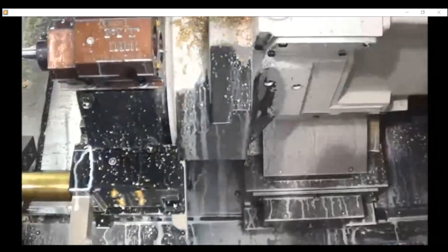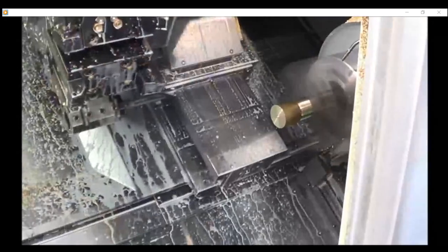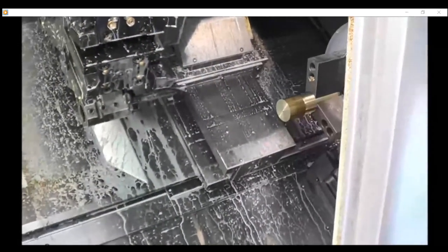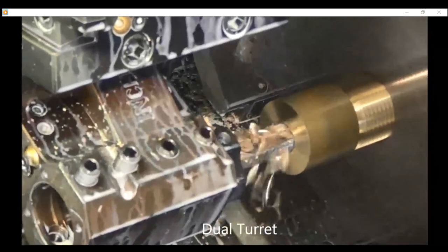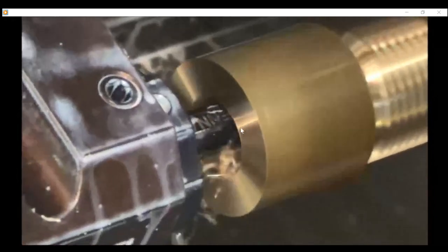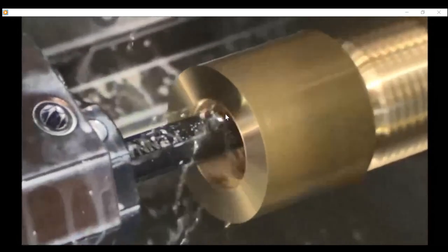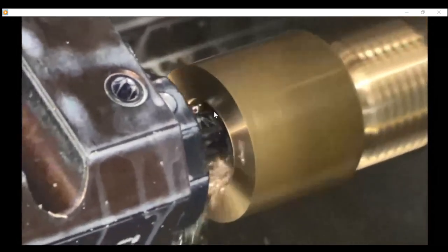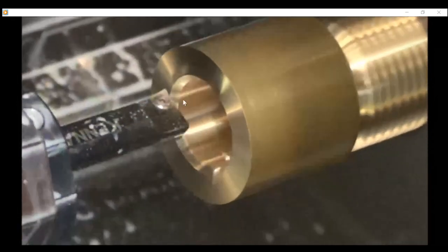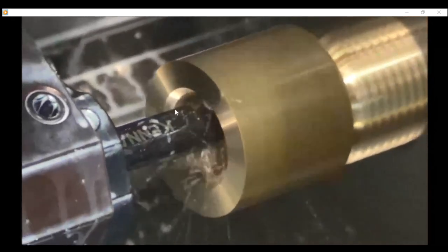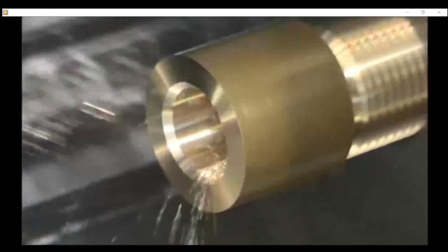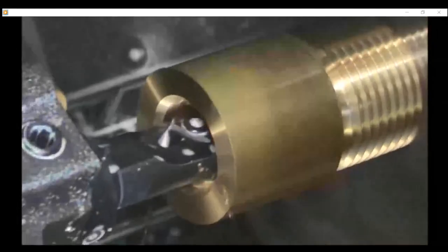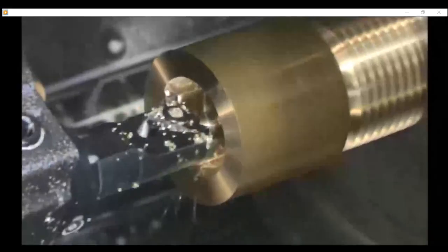Then there is relative motion, all the time, between the tool and the workpiece. Then you can obtain what you see here. And then drilling the other side, drilling here, and then you also see this is internal. Whatever you do outside, external, you can do internal. Whatever you do in external turning, you can do in internal turning. Whatever is taper here, this is a taper. This is a straight cut. This is a taper cut. You can also do threading, outer surface threading, inner surface threading. So whatever you do on the external surface, you can also do on the internal surface.